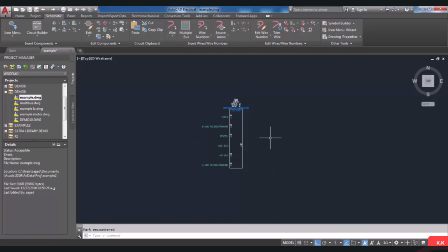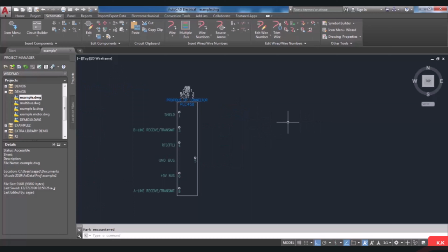Sometimes you need to break the module and insert the remaining parts of it in another area or another drawing, so you can skip the input-output for adding a space. As you remember, I mentioned this option in the previous part, which was in the module layout, the Allow spaces breaks option. Now back to the Insert PLC Parametric tool.